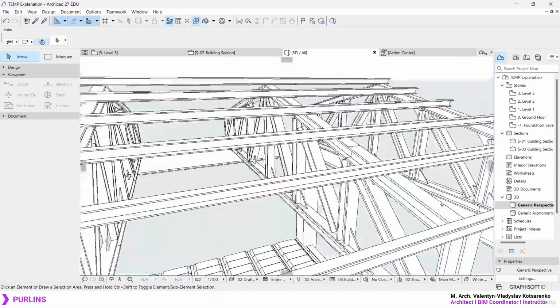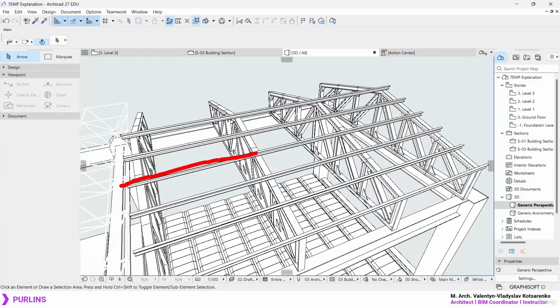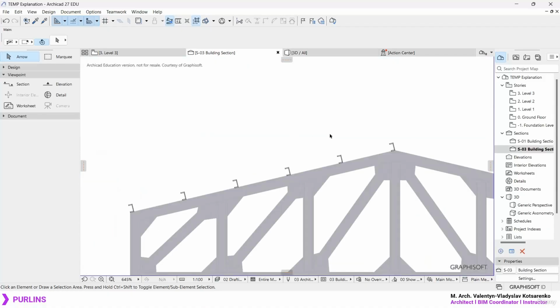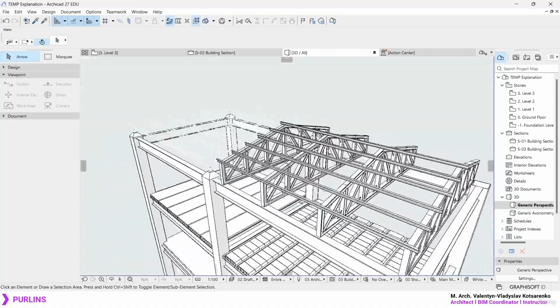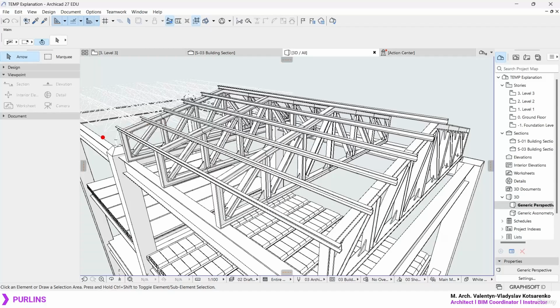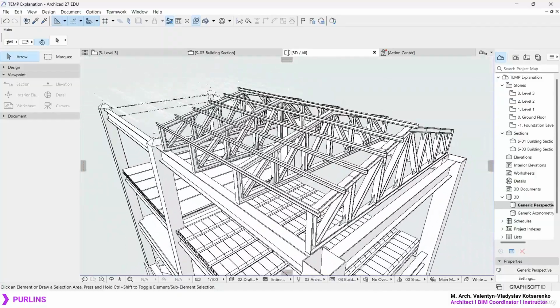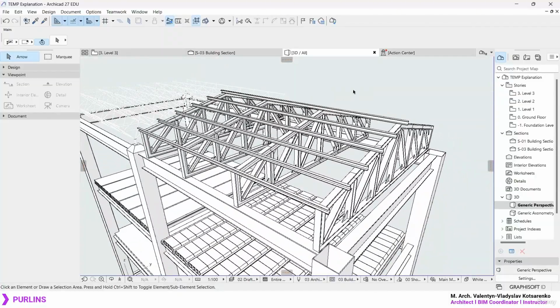And if you notice, it's not that hard. You just need to start off solving the length with your profile, okay, on the floor plan view, and then when you have the length, doesn't matter the position, simply create a cut section view, and in the cut section view you can pretty much solve everything. So having created the purlins, now in the next lesson we can continue and simply position the last element, which is going to be the sloped metal sheet roofing, or the metal sheet roofing with an angle. But beforehand, take a minute, make sure to position correctly all the purlins you require, and in the next lesson we will continue with the other element.